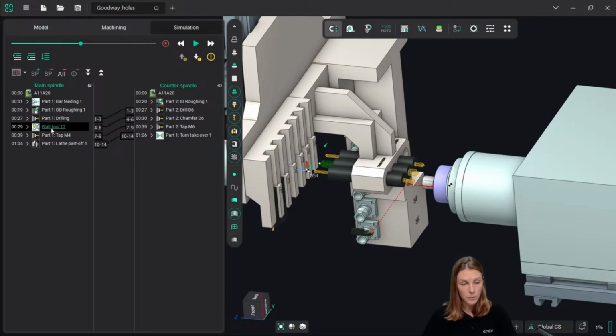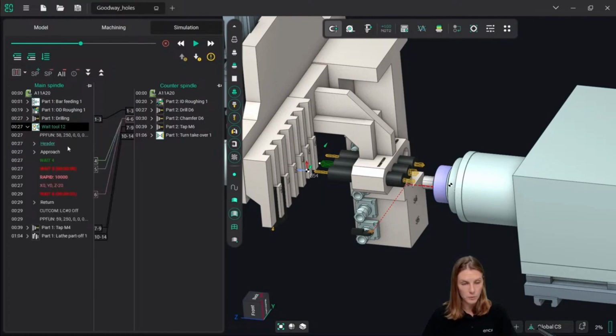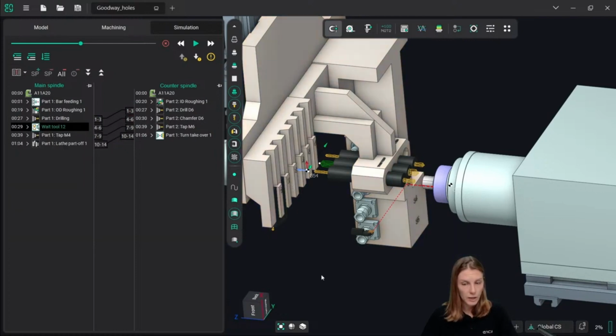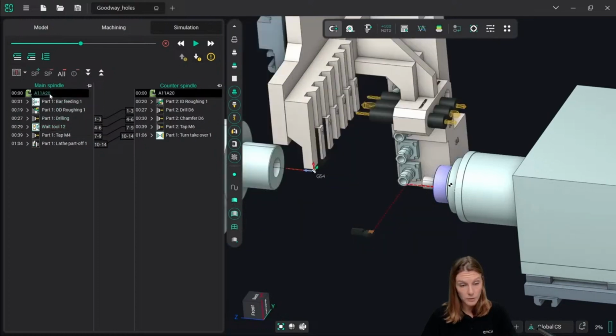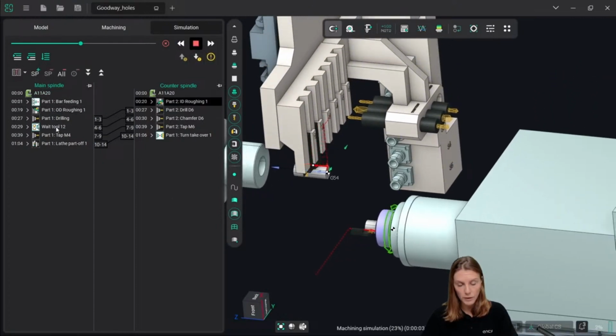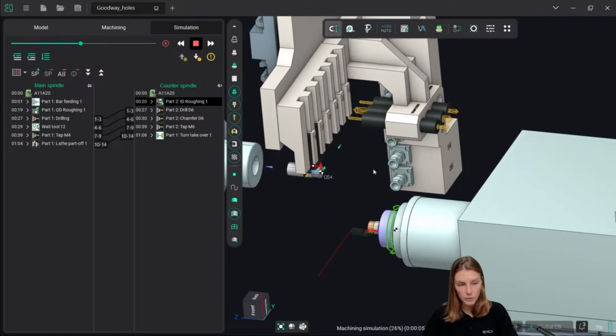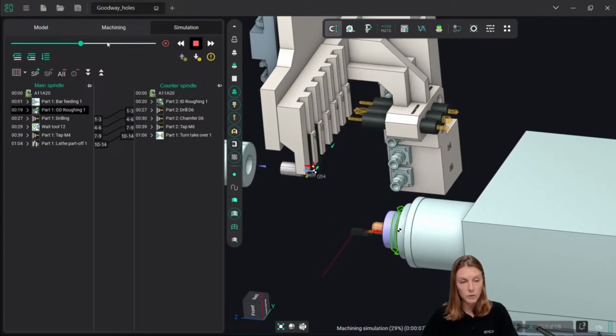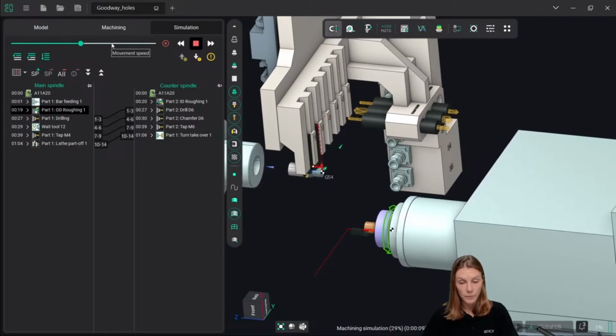It's not a cutting operation, it's kind of an empty tool path operation, but it's really needed to be there, because in this case we don't ruin the structure and we can make all the rest of the machining without any time conflicts. So let's start from the beginning and take a look at what will happen at this point when we have deleted the chamfering and replaced it with the wait tool code.